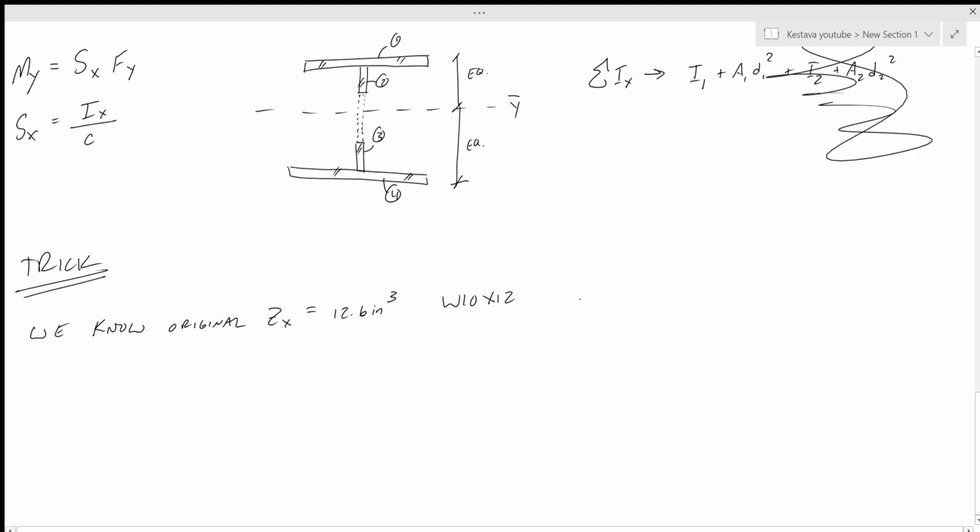That's kind of nice because now it's a nice geometry. It's 6 inches tall because it's a 6-inch penetration, and it goes through the web of the member, so the thickness of the web. And since our section is plastic, we know that Z equals BD squared over 4. B is the same thing as the thickness of the web here, that's the base width.